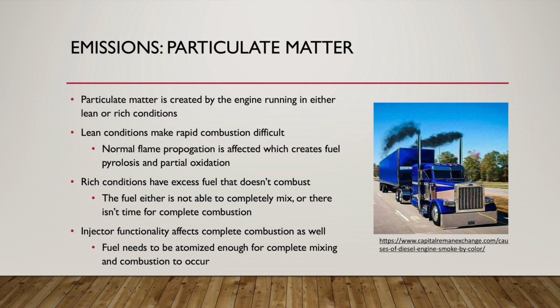So that's going to create fuel pyrolysis and partial oxidation. So that's where we're going to have not complete combustion. And we're probably not going to make as much power because we're not burning how we should. Now with rich conditions there is excess fuel that doesn't combust. So we still don't have complete combustion because we have extra fuel.